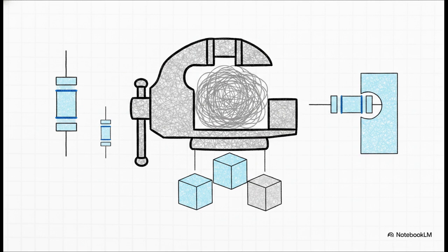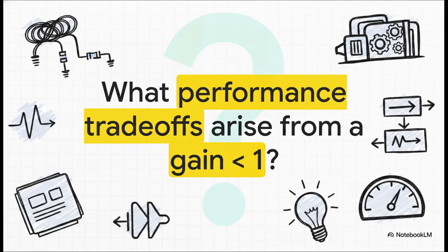When you physically build your board with these exact constraints in place, everything collapses beautifully into the ideal approximated parameters for a PID system. Your gain K becomes R2 over R1, your derivative time constant TD becomes R1 times C1, and your integral time constant TI becomes R1 times C2. You now know exactly how to physically implement a full PID controller using nothing but resistors and capacitors.